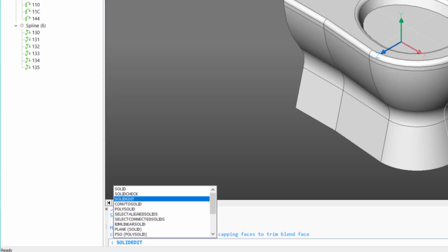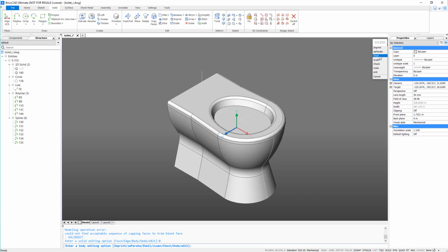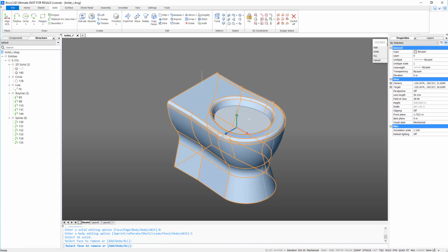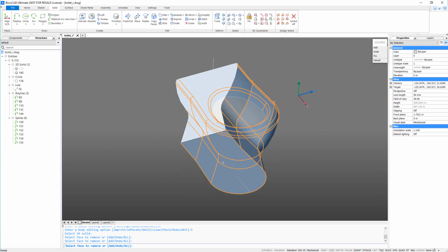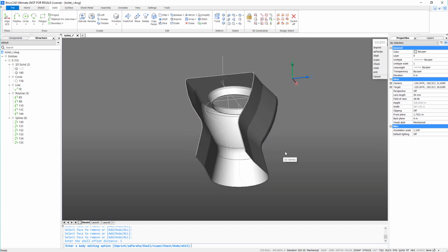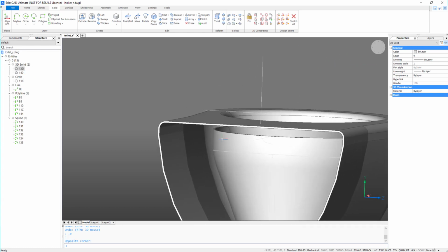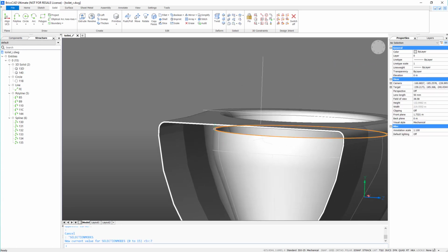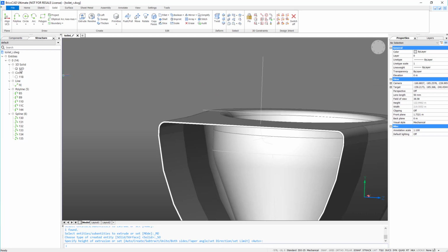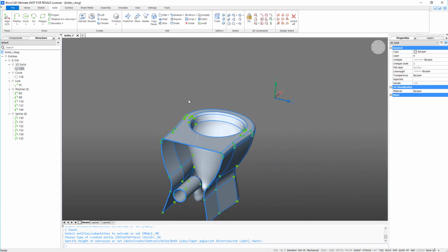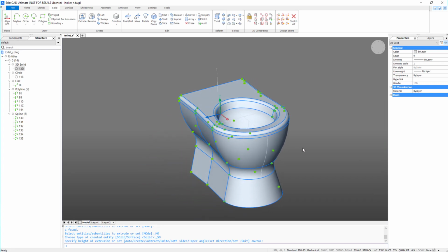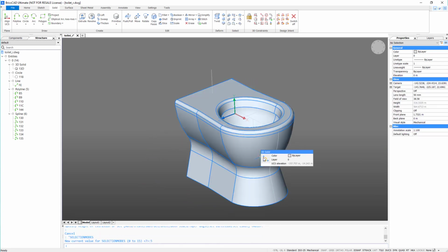Using the SolidEdit Body and Shell command, remove the material from the hole, the back and the base. Now show the U-bend and extrude the top face upwards to touch the main stool. Notice that this is now one solid in the structure browser. Hide this solid.